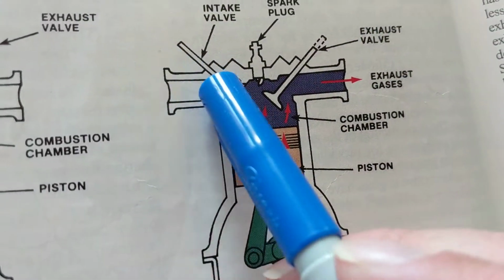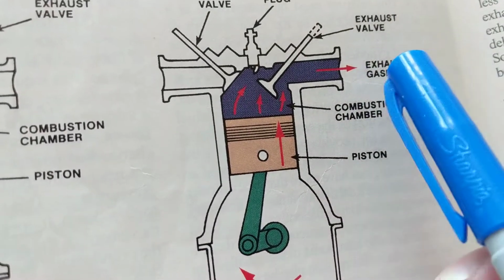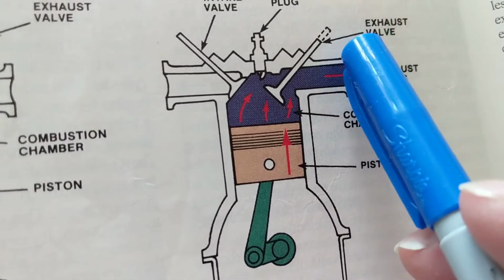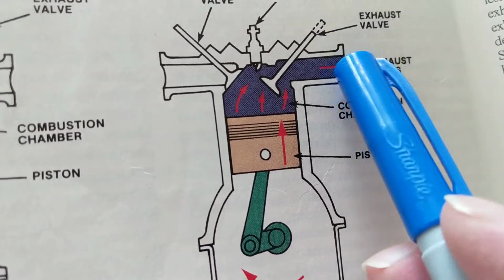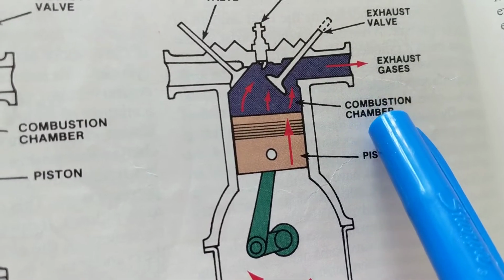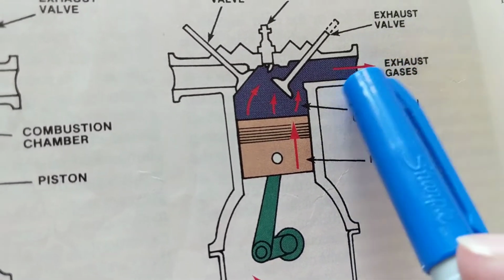We know how much air fuel was in here. We know how much to correct when it goes out. Maybe there was too much fuel. Maybe there was less fuel. Maybe it's too much air, less air, whatever. Oxygen sensors are here on the exhaust manifold, measuring how much oxygen is in the air-fuel mixture.